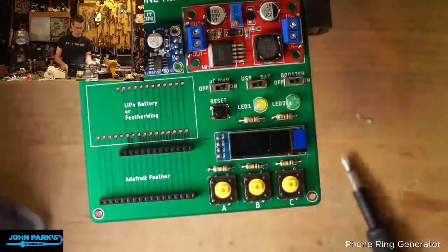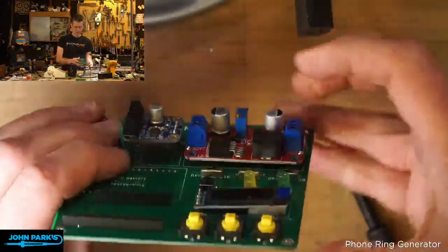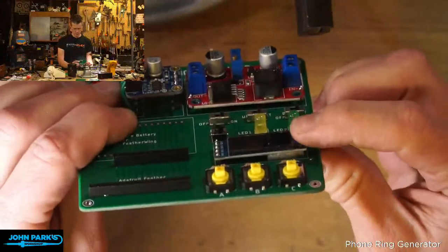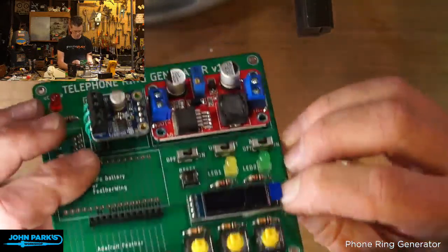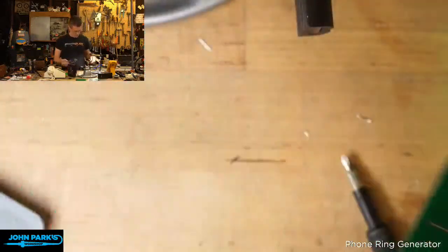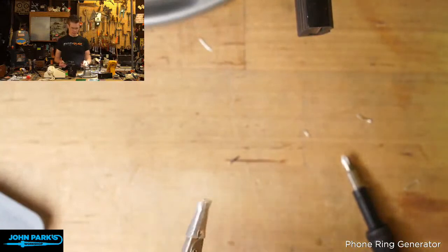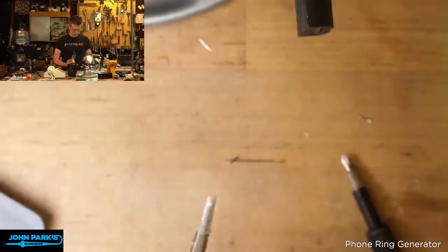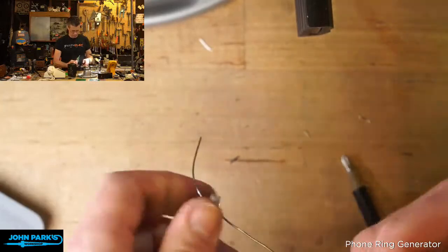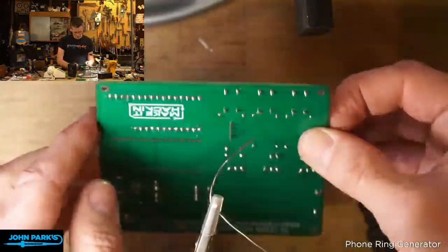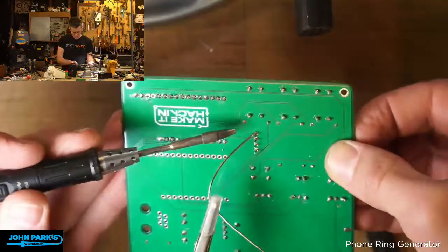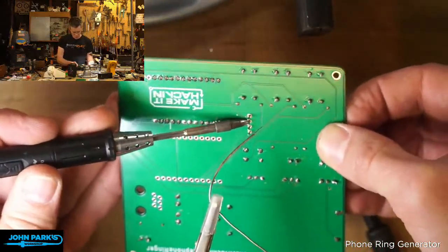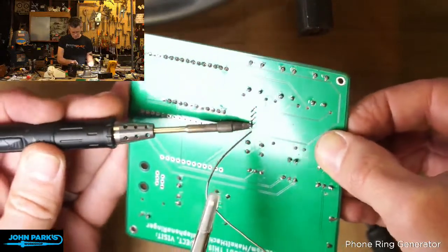Okay, so you can see that is maybe a little too thick, but what I'll do is compress that board down like that, not the screen, and then solder that into place, and it should be pretty nice. So here's a case again where I'm going to grab a helping hand with my solder in it. A fun skill to have is to also solder left-handed sometimes when that's more convenient. So square is the ground on these, so I'm not going to do that one first.